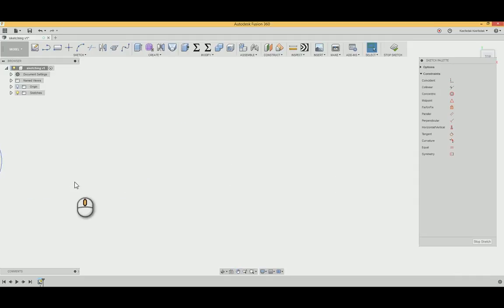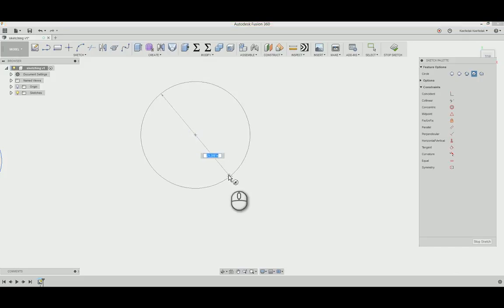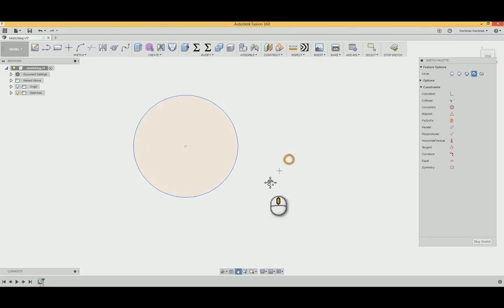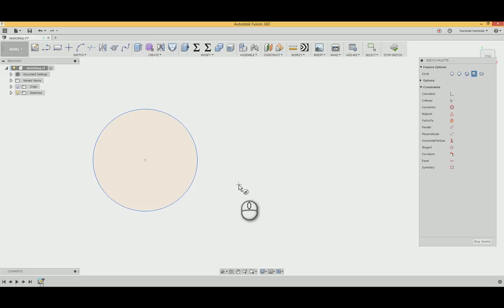I'm going to show you how you use it automatically. Okay? So you're going to hit C for circle, draw a circle. And once you draw your circle, hit L on your keyboard. Now watch. There are two cool things you can do with a line on a circle. If I let the cursor just touch, I'm going to click and hold.